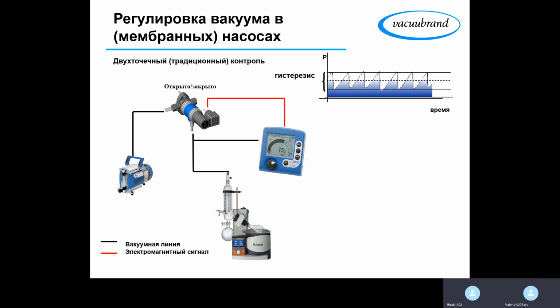I see. There is a rule of thumb which says that when we are distilling, the amount of the condensate that we have in the condenser should not reach the height of 2/3 of the condenser.